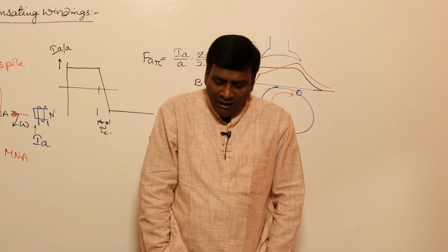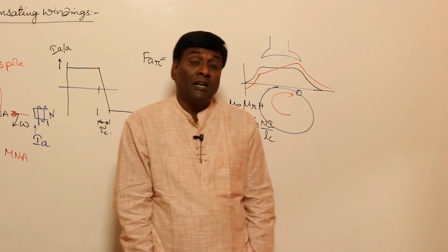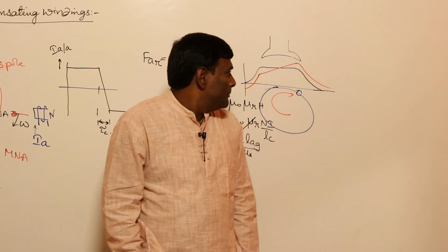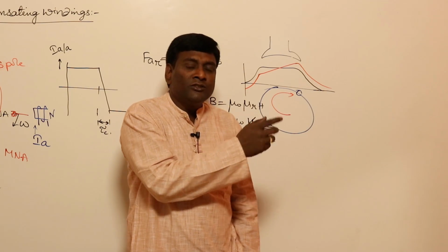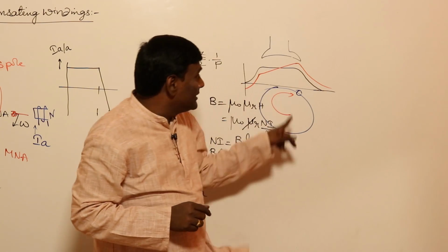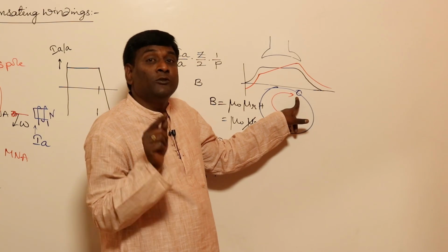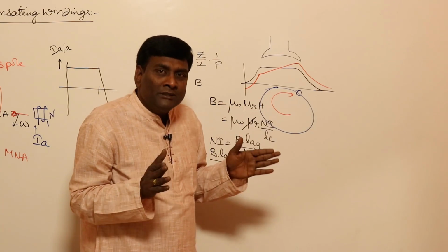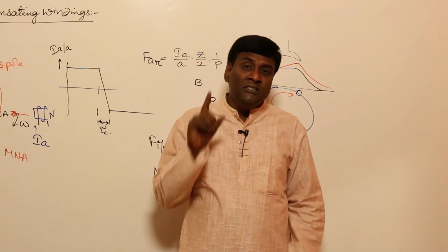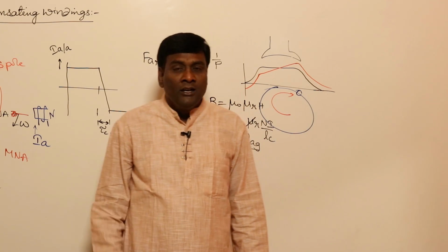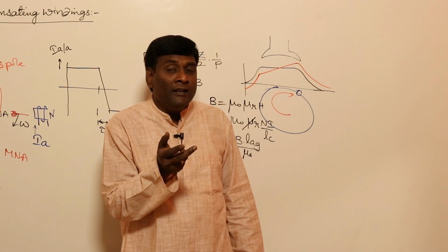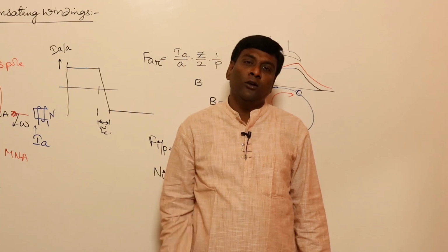Already our DC machine is not a very useful machine. Because of these flux variations and the statically induced voltage, the stress upon the insulation is going to be high, so we may have to compensate. Normally all DC machines will have interpole winding, but when load variations are tremendously high, we may have to think of compensating winding also.